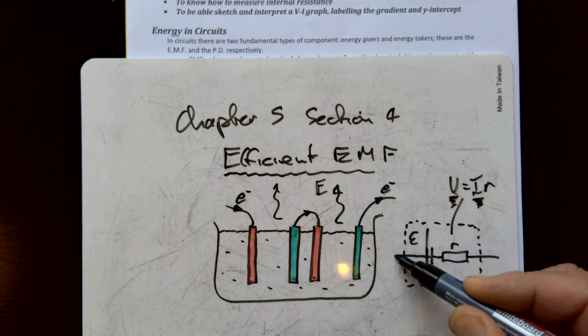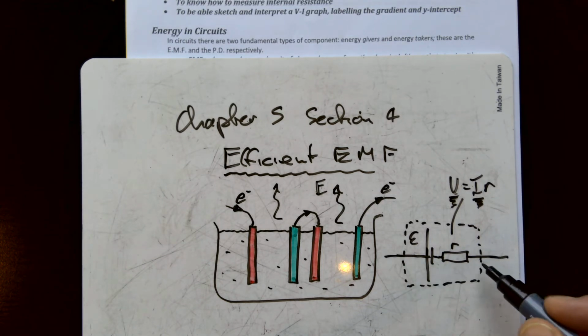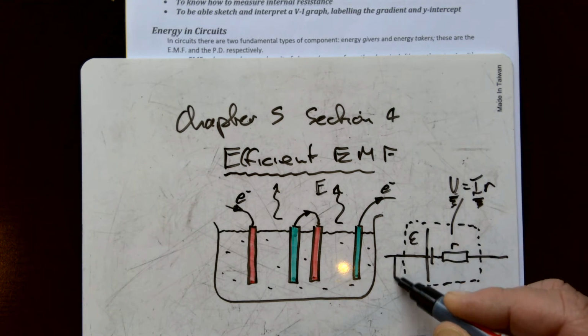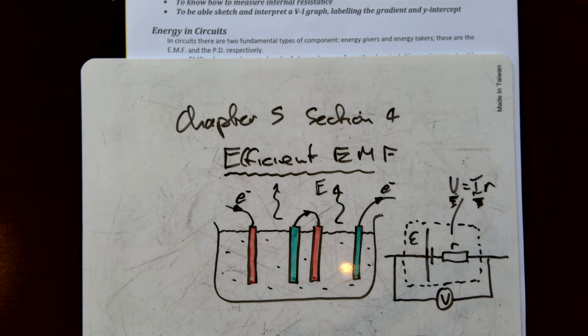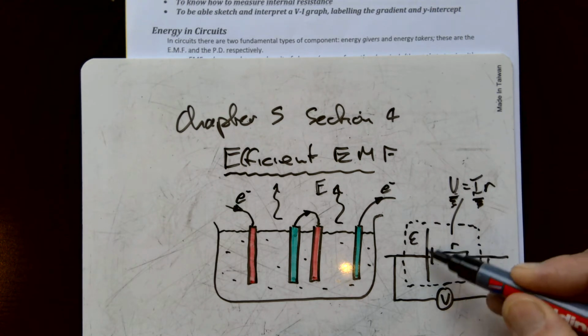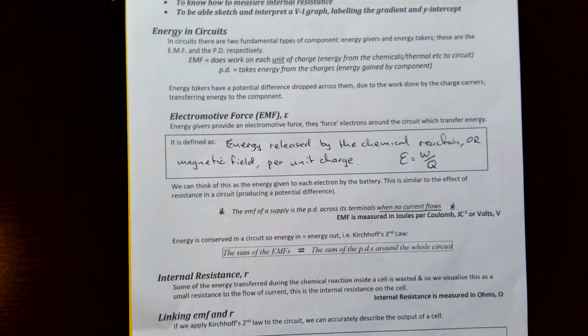So we're going to think about the battery as a whole, that includes both of them, and we're going to look at what comes out of the terminals. So we will call this the terminal voltage. If you stick a voltmeter on your power supply, it's actually what you get out, it's not necessarily what's being created. Little r, very simple.